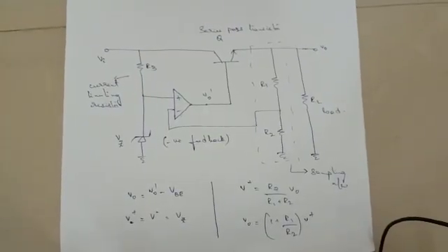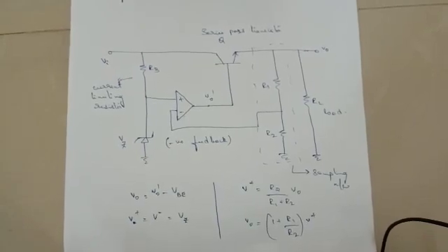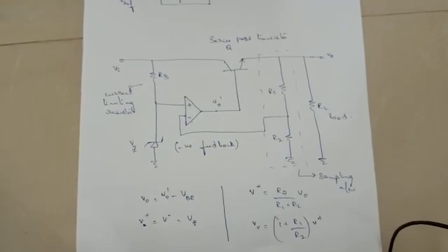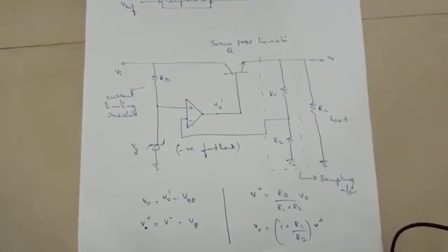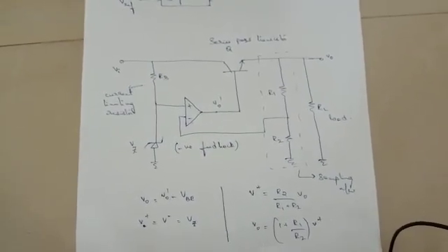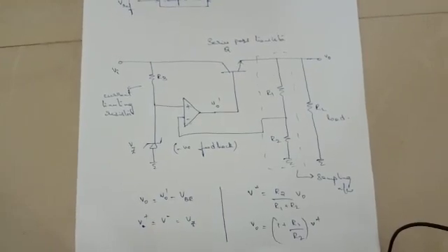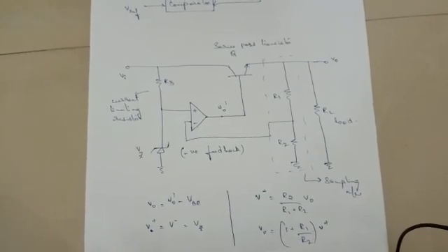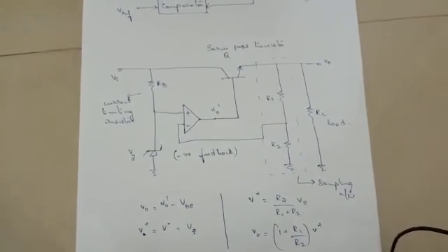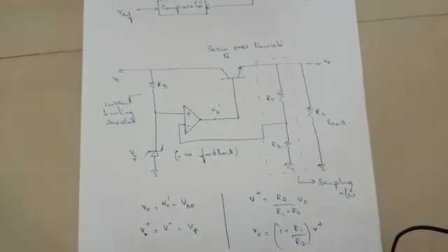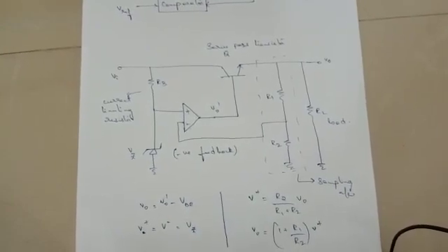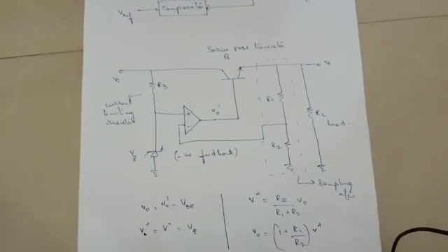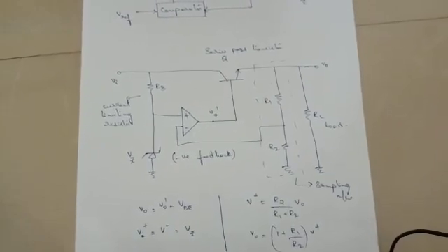The circuit of series voltage regulator is as shown below. The resistor R3 followed by a Zener diode. Zener diode is serving the purpose of reference voltage as shown in the previous block diagram. The resistor R3 will be acting as a current limiting resistor, therefore protecting the transistor from getting damaged, at the same time limiting the value of the load current. The transistor is placed as a series component, so it is called as series pass transistor.